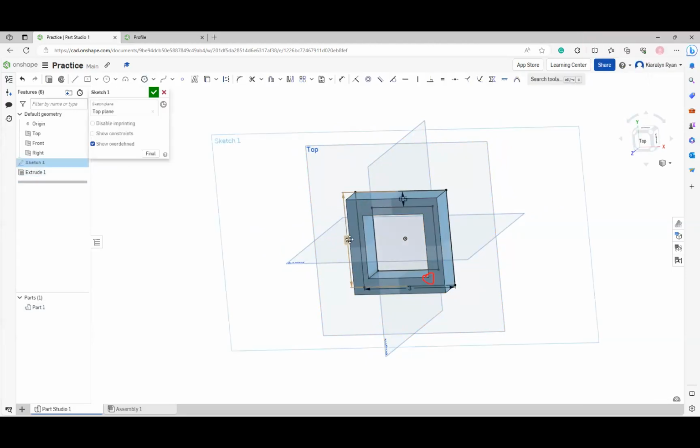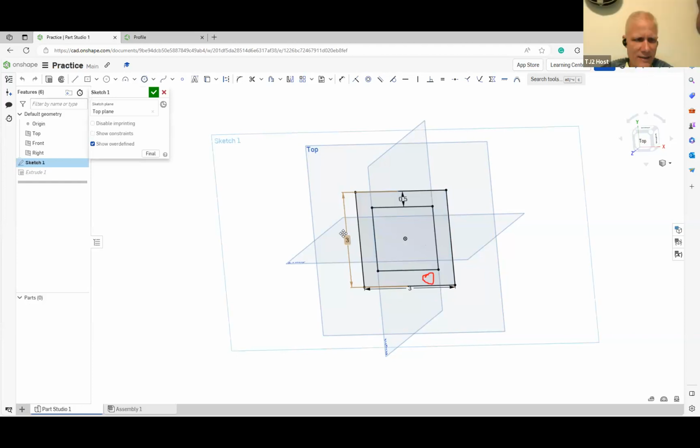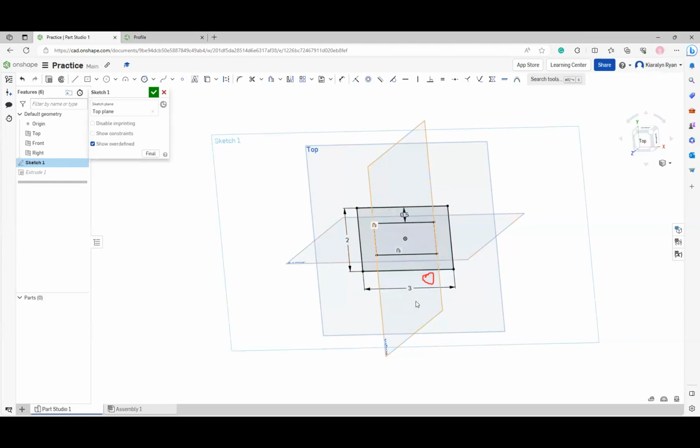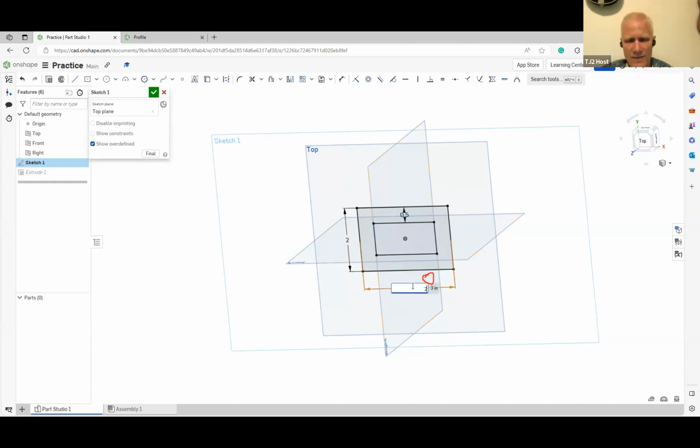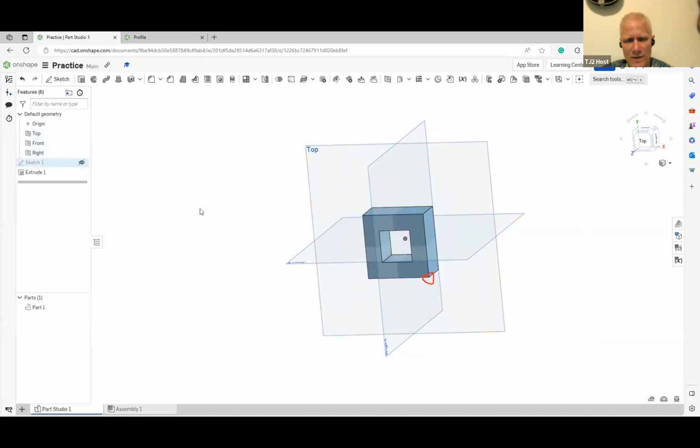So how do I? Okay, so right click on the sketch, and then hit edit. Yeah, there, now you're in. Okay. So make it 2 by 2. Good. And make it be, no, we need it to be 1/8 of an inch thick.